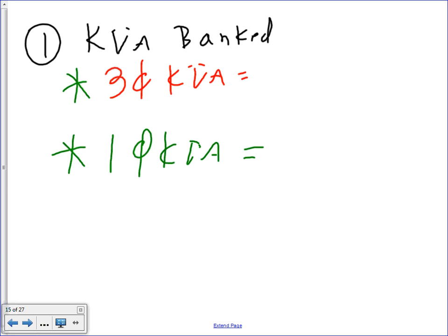There are two kVA banks in this case, guys. Good discussion. The first kVA is for the three phase. So the three phase, how many do I have? Each one of them is going to contribute 100 plus 100 plus 100. Everybody understand why for the three phase each one of them is going to contribute 100? Why do you think I didn't put 150 here? Because if this guy is going to push 150, it will force this guy to push 150.